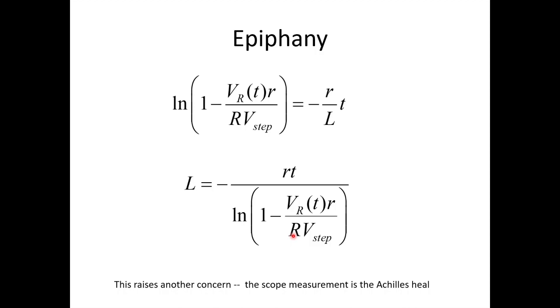And the ramp resistor isn't going to change more than 50 parts per million with temperature, so that's going to be a very well-known resistor. The voltage step we're going to calibrate with our 6.5 digit Agilent digital multimeter, so that step will be very precise. And our time base is going to be very precise because we've gotten all our time bases down to better than 10 parts per million.